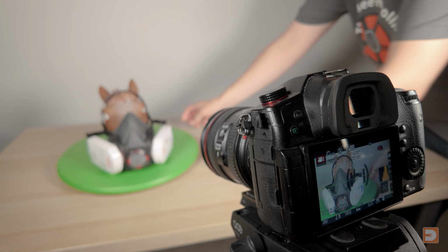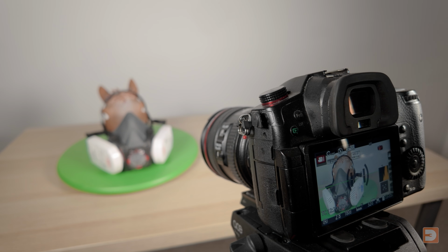As I mentioned earlier, for photogrammetry, you want to take photos of your object from every angle from multiple levels. When you're working with smaller objects, it may be tempting to put your camera on a tripod and then put your object on a turntable in front of the camera, rotating the turntable between each photo. This method works great for some types of 3D scanning, but for photogrammetry it's generally not recommended. Photogrammetry uses everything it can see in the photos you take, including anything in the background. It then uses this information to try and figure out the camera positions and therefore the geometry of your object.